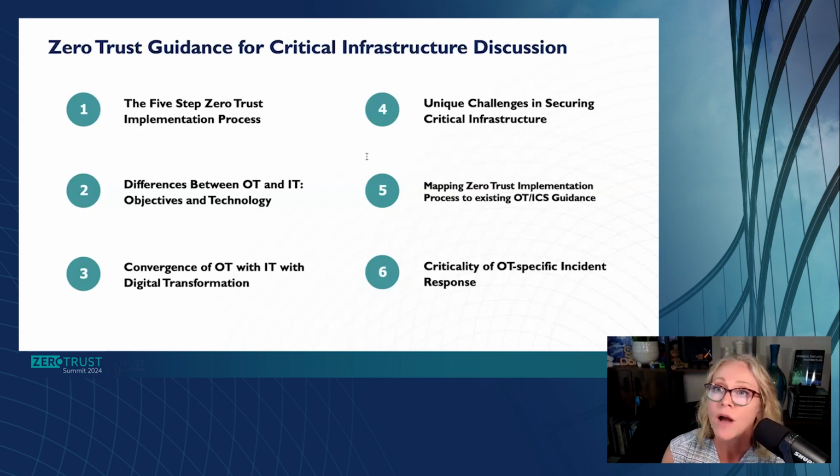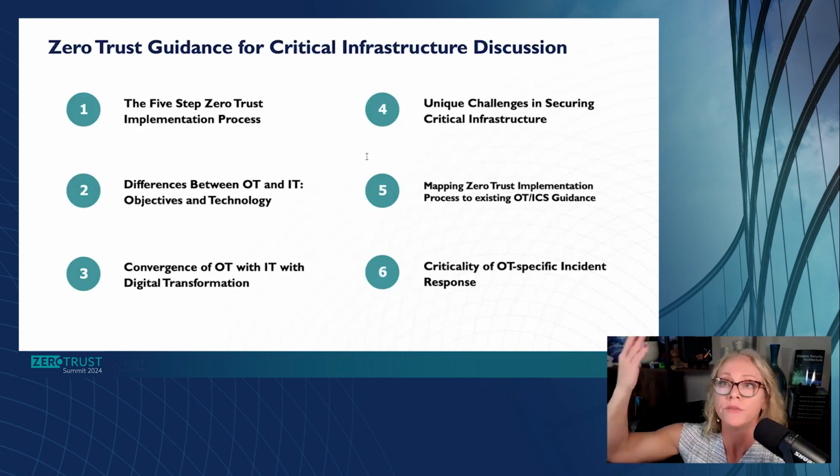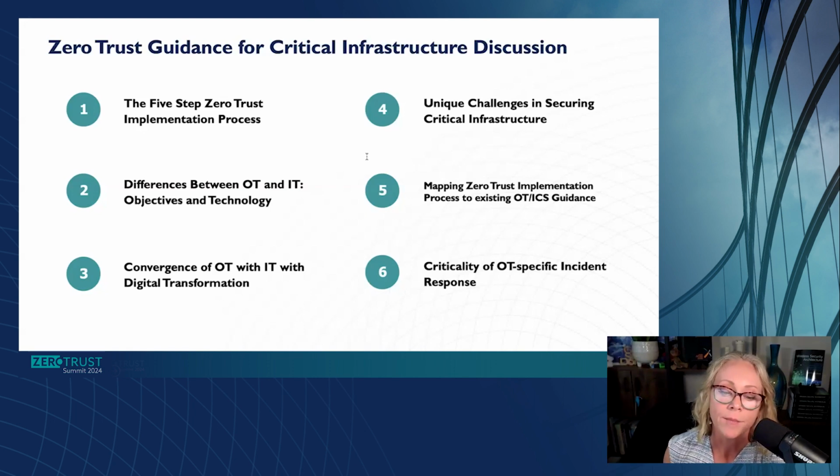But yeah, I mean, you've got business systems, manufacturing systems. Typically we see things going out from the OT environment into something else, right? Unidirectionally, where we're pushing that up into something in the enterprise IT, like billing, or up into the cloud for analysis. I think where we get a little twitchy still, because again, the Purdue model is meant for a conversation starter.